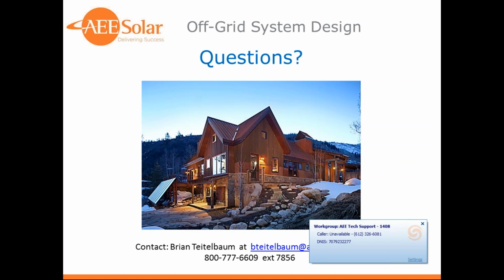Okay, that's an important point. You do have to allow for surge, especially for big items like pumps or compressors. Most of the inverters will surge to up to twice their rating. So typically if you had, say, a 6 kilowatt inverter, you can typically get 10 to 12 kilowatts of surge power for up to 5 seconds.